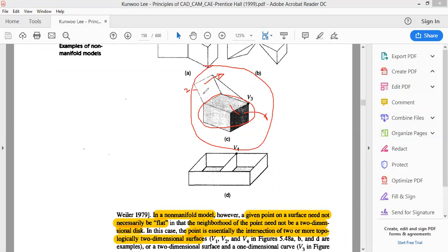So to obtain better results and accurate values, we have to go for shell elements over here, because the thickness is very less in the non-manifold portions, right? So this flexibility has to be there. We cannot always expect that whenever we do any analysis, it is always going to be only with respect to one type of mesh element.